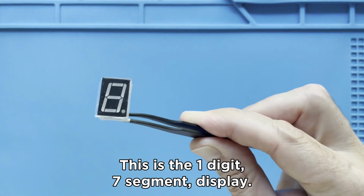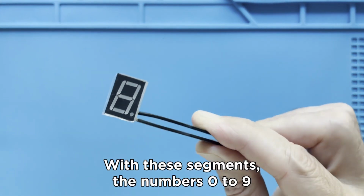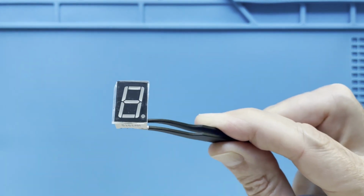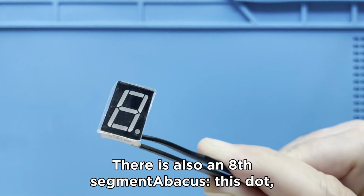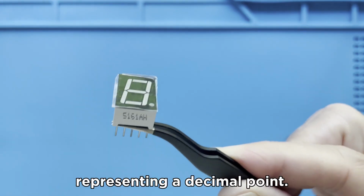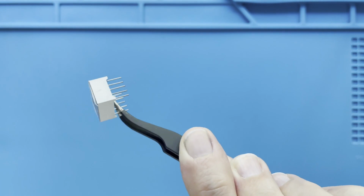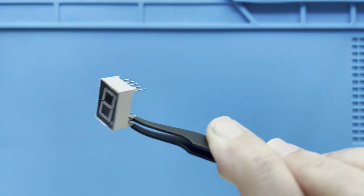This is the 1-digit 7-segment display. With these segments, the numbers 0 to 9 can be created. The segments are in fact LEDs. There is also an 8th segment, this dot, representing a decimal point. There are 10 pins coming out from the back of the display.